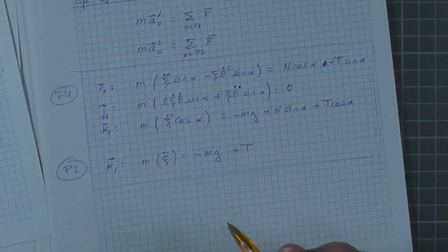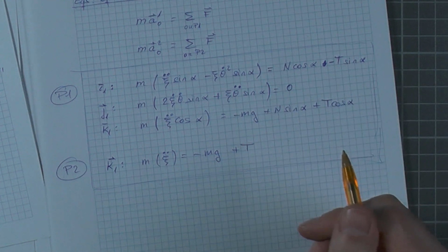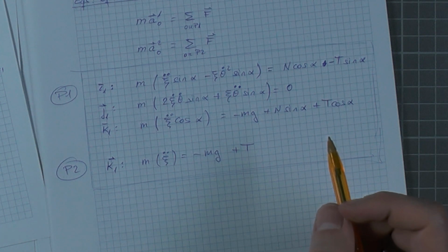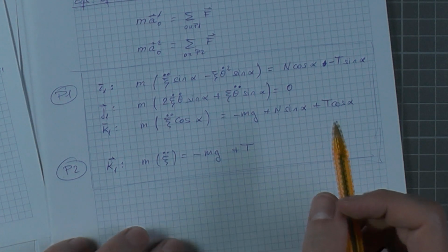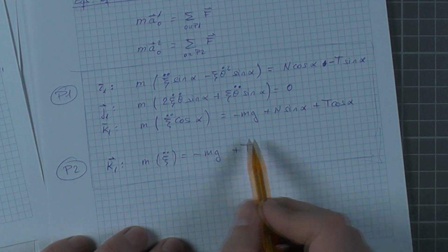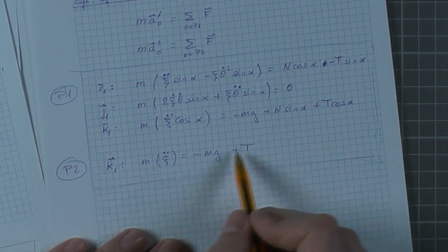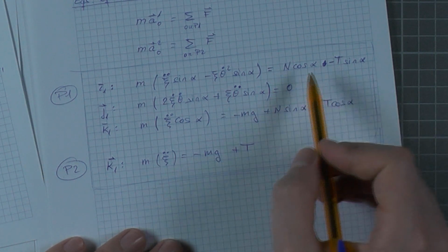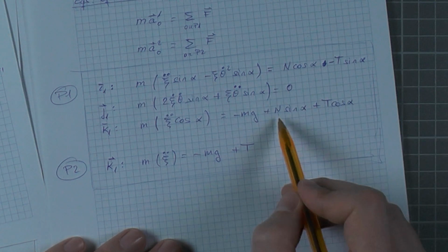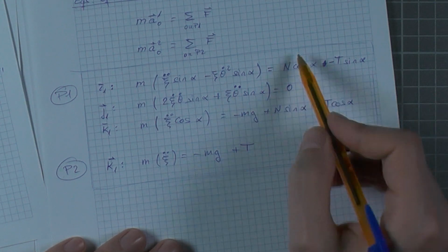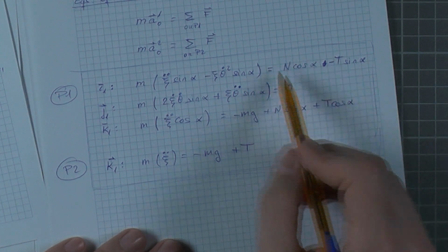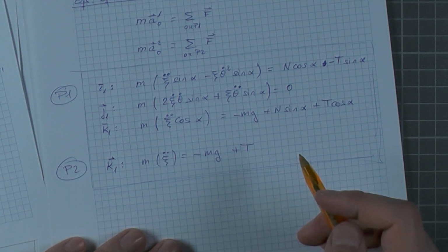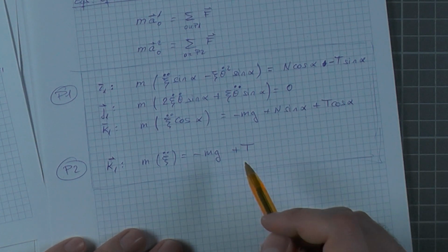Usually what we do with such a system of equations is to work out a linear combination of equations that does not contain the reaction forces. For example, if we wanted, we could solve for t in this equation and use that to eliminate t in these two equations over here. Then if we multiply this equation by sine and this equation by cosine of alpha, and we subtract the two equations, the terms involving n would also disappear. So that is also useful to eliminate n.